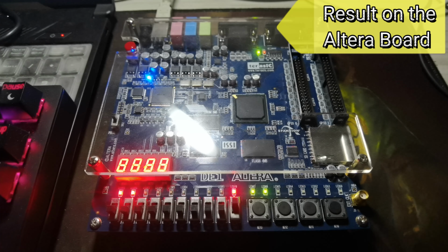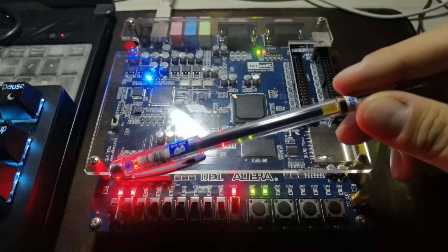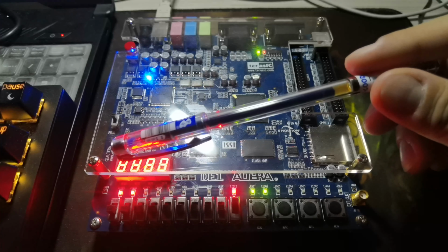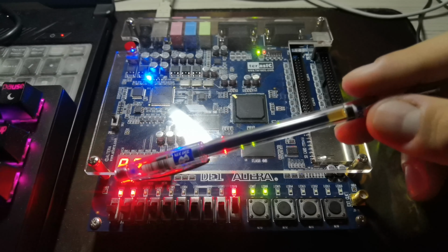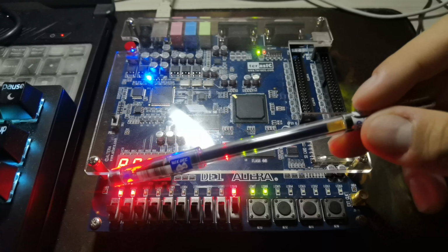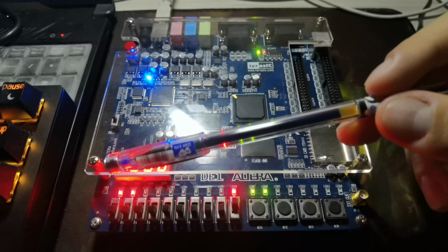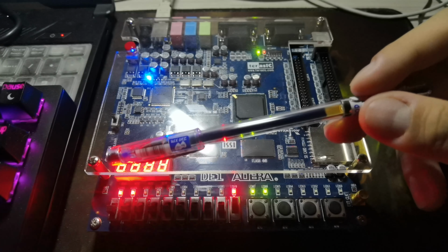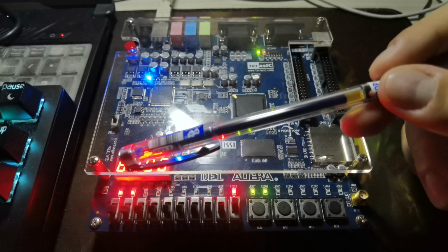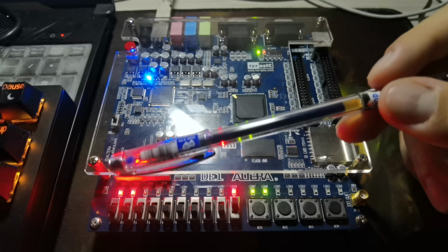Before I start my program, I would like to clarify something. The first two red LEDs indicate the memory bank selected. If both red LEDs are off, memory bank 0 is selected. When LED 9 is off and LED 8 is lit up, memory bank 1 is selected. When LED 9 is lit up and LED 8 is off, memory bank 3 is selected. If both red LEDs are lit up, memory bank 4 is selected.